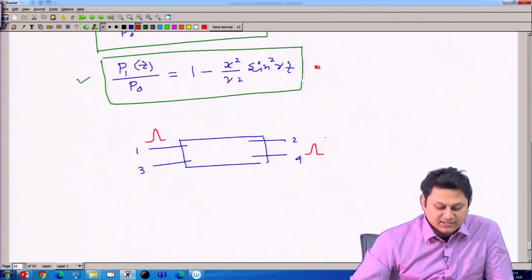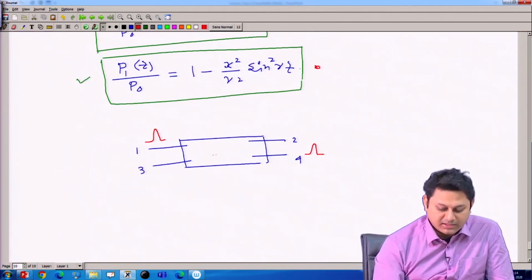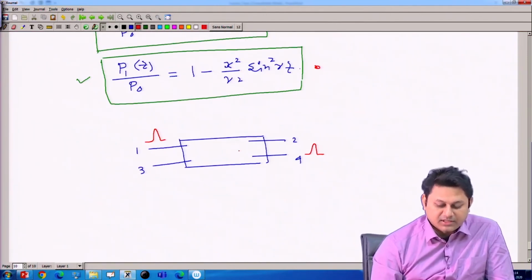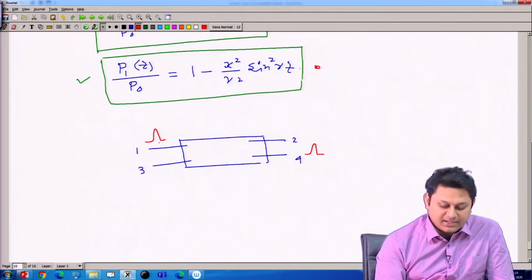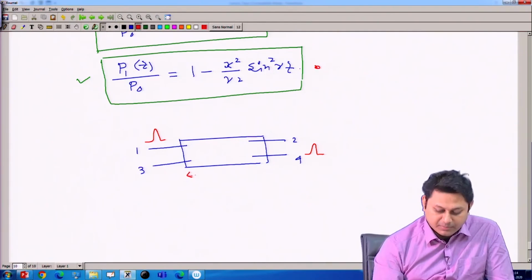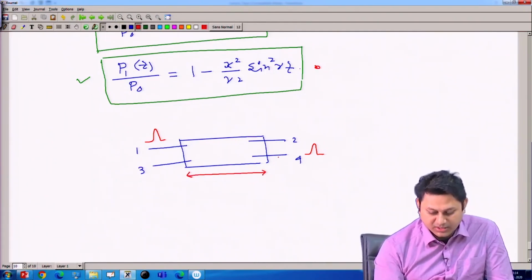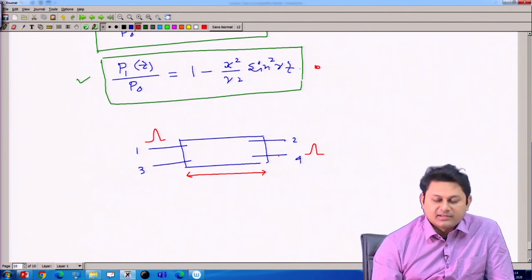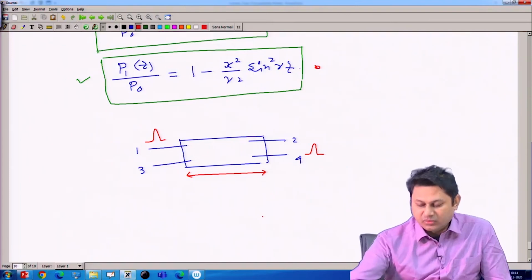These two equations suggest that if we have two waveguides placed very close to each other and behaving like a coupler, then the energy can couple from one waveguide to another waveguide, and there is a periodic transfer of energy from one waveguide to another. So, if you cut my coupler in such a way that this energy is completely transferred to here, then I can use this as a switch, an optical switch. So, with this note I would like to conclude.